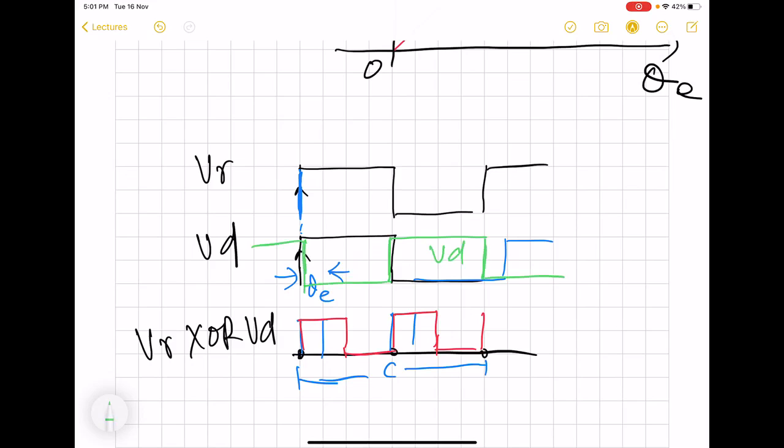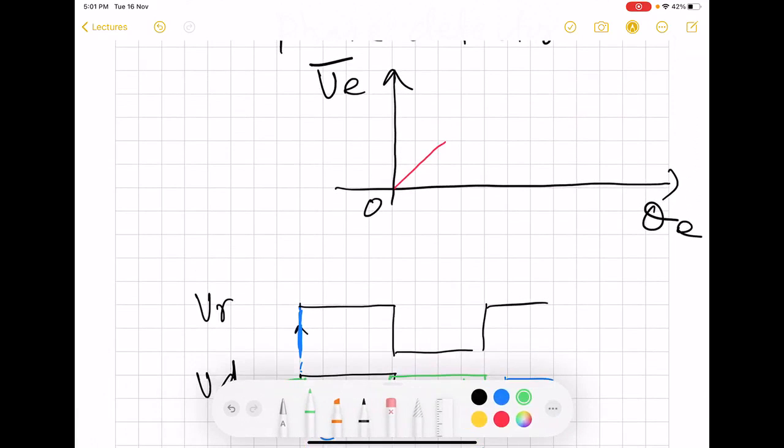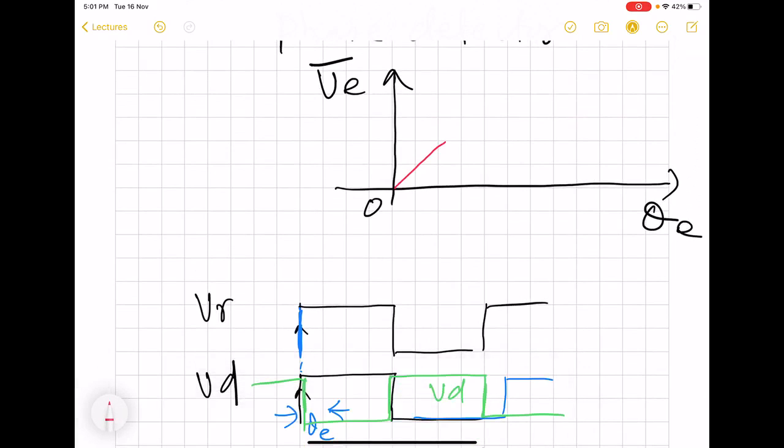For this case, what we are going to get is a pulse which will be high for the first half and then high for the second half as well. So this is the maximum anti-overlap. We know that XOR basically checks the anti-overlap, that means the moment when one is high, the other is low. So this waveform is going to increase for phase error up to pi.